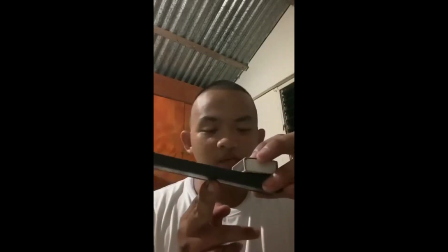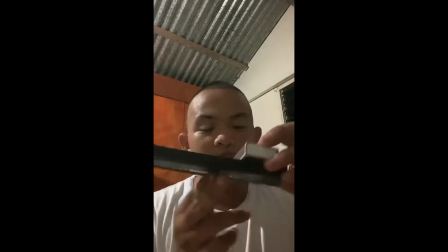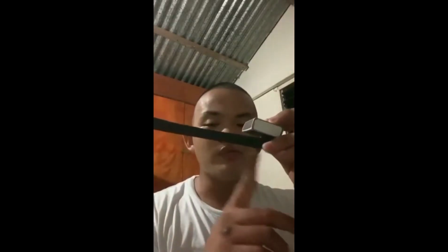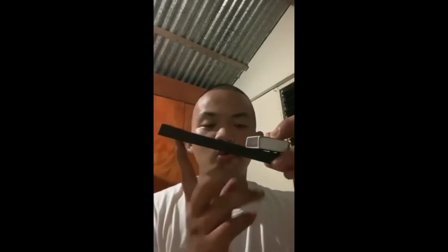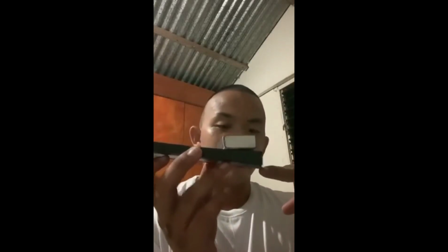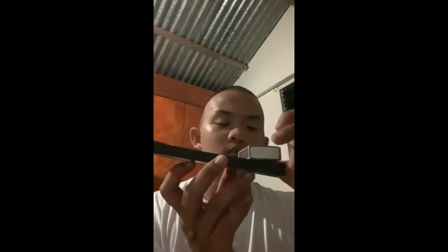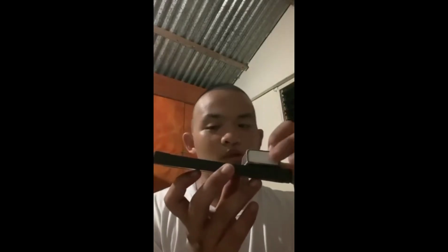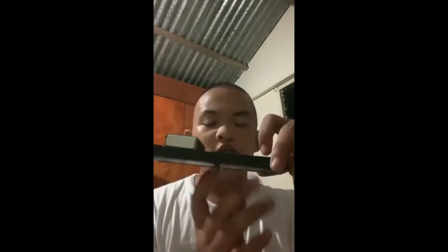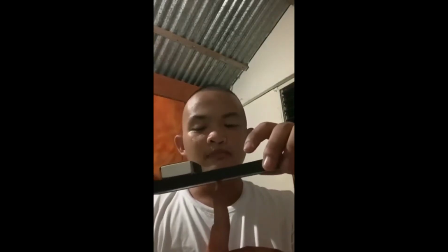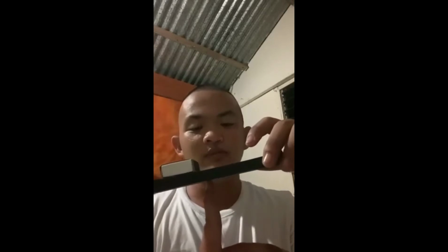So we put an object here on the aft, which causes the aft to go down. The forward rises up. The level of draught at the aft becomes lower, and the level of draught at the forward becomes higher. So for change of trim, whenever the weight moves from its initial position to new positions, the gravity and buoyancy change.